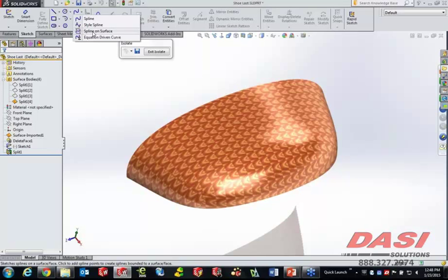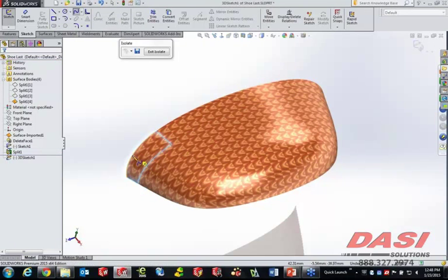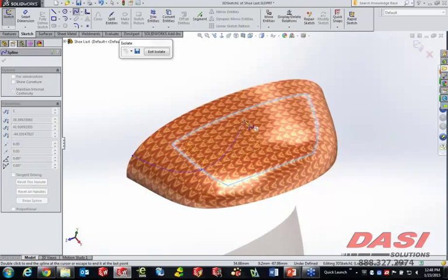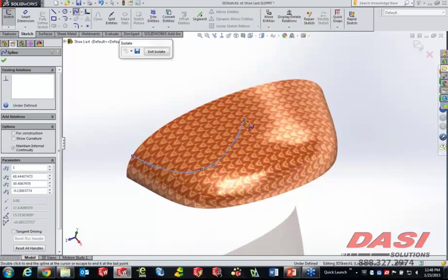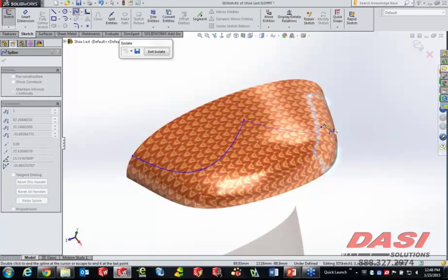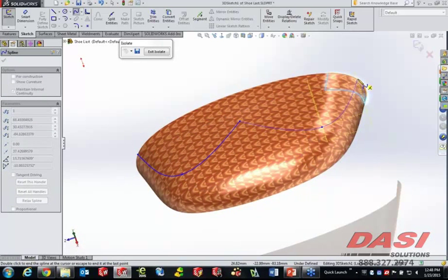So with this tool, we're going to just go ahead and select it and simply draw on this surface. And what's odd about this, and I'm saying odd in a very good way, is that it appears from the user that we're just kind of adding coincident points. So I'm just clicking once, clicking a second time, and then I'm going to infer to this edge back here and just double click to finish it.